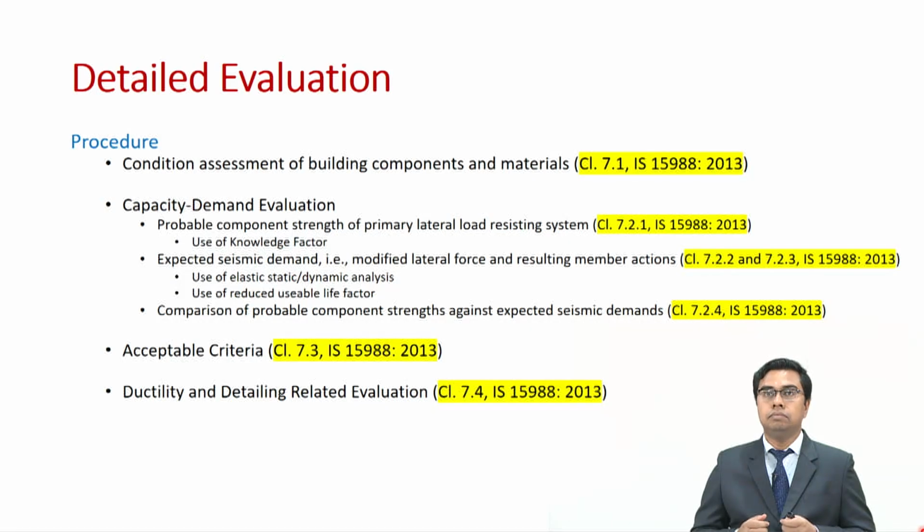Once we are confirmed that we need to conduct detailed evaluation, then we have to follow some procedure. So, the first step in the detailed evaluation shall be to assess the condition of the building components and materials. This will include some non-destructive testing of the building as well. This is based on clause 7.1 of IS 15988/2013. I hope you have the copy of the code ready with you.